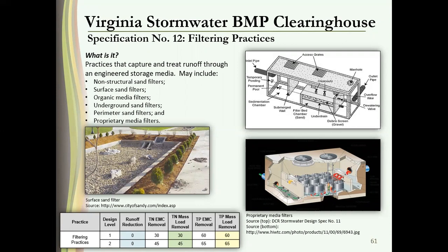And it does the work for you. Here you would actually have to design this yourself, but it's basically the same thing. It's usually an area where all of your stormwater comes together. Great places for these are parking lots, because you can just put in some curb cuts. All of your water is sheet flowing, goes through the curb cut, and then can go into your filtration practice.